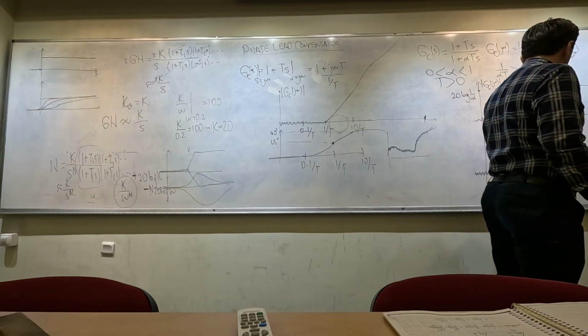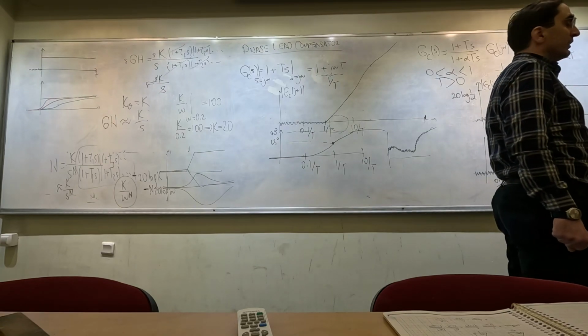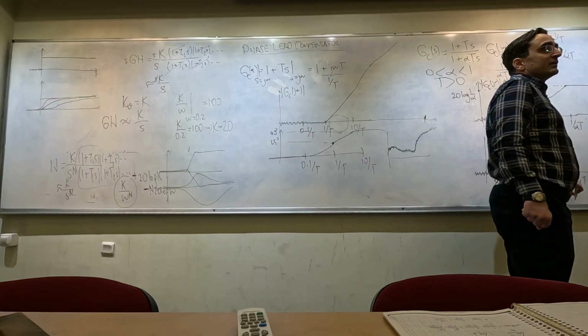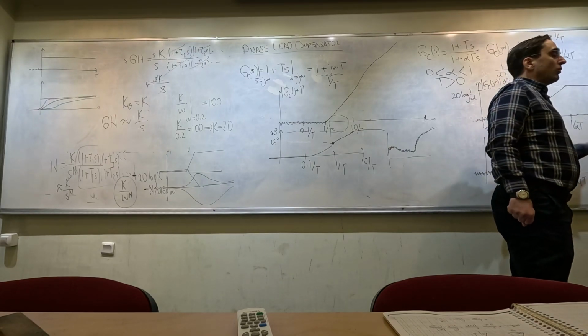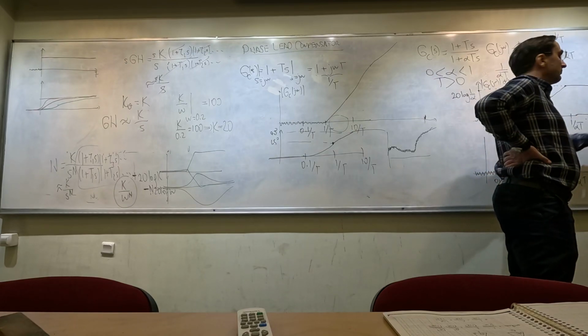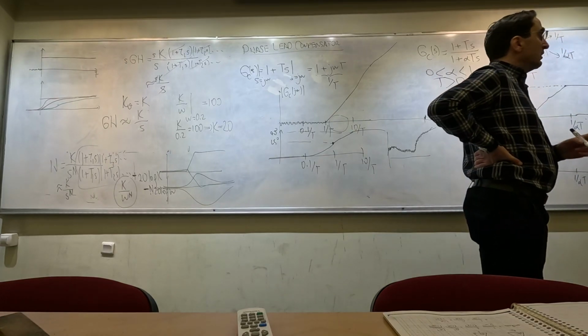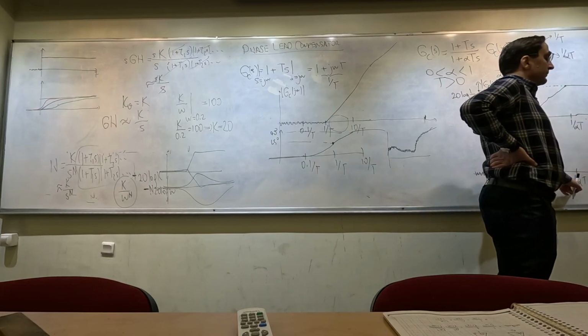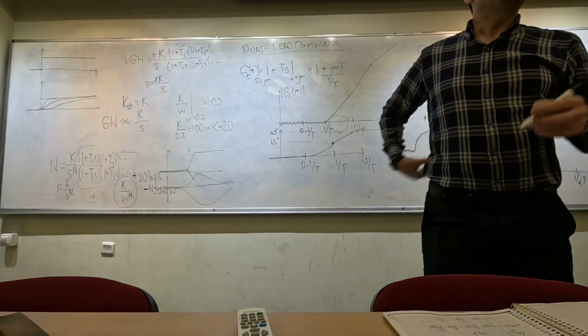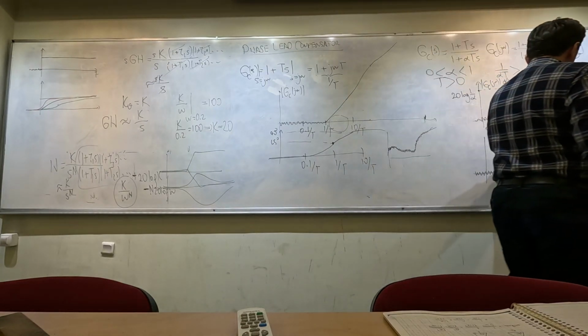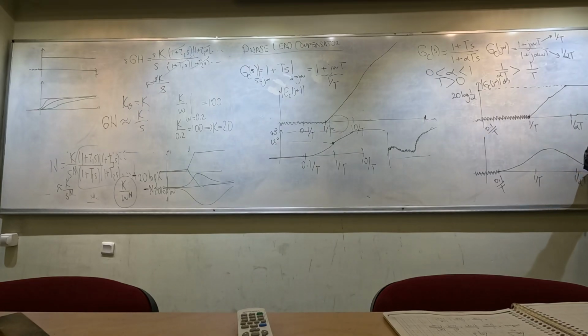So we're going to come here and the phase is going to increase. If this pole was not here, if this corner frequency was not here, then we would pass through and go to the 90 degrees there. But now, because of this 1 over alpha t corner frequency, what is going to happen? Phase is going to start decreasing, right? So from a point, we're going to have a phase given like this. All right, so this is a phase lead compensator.